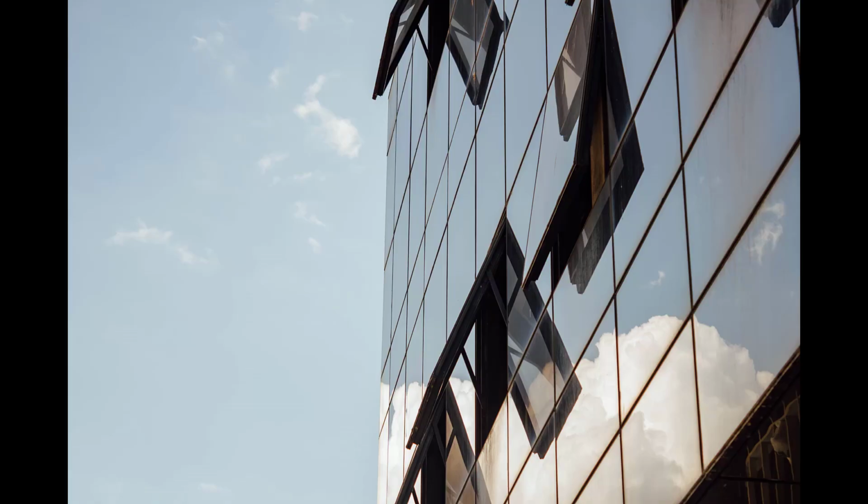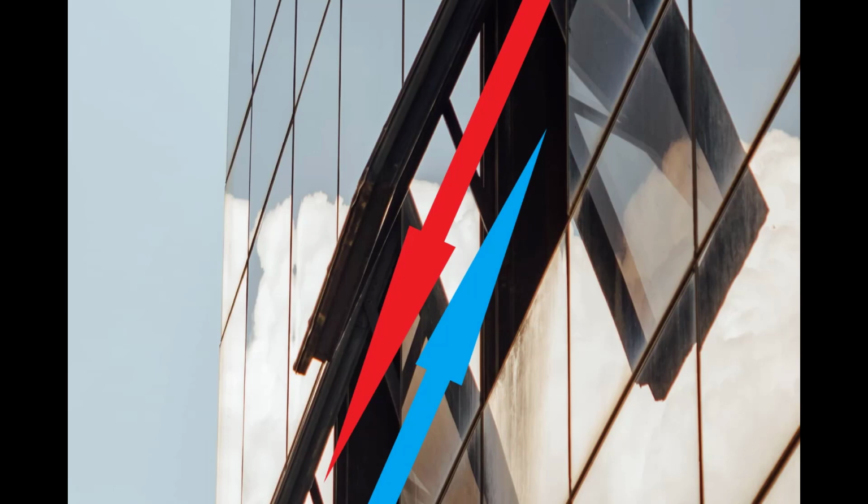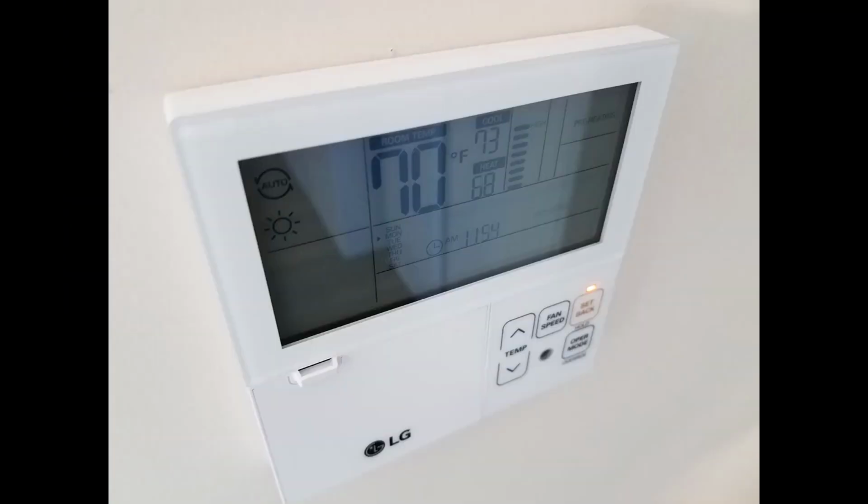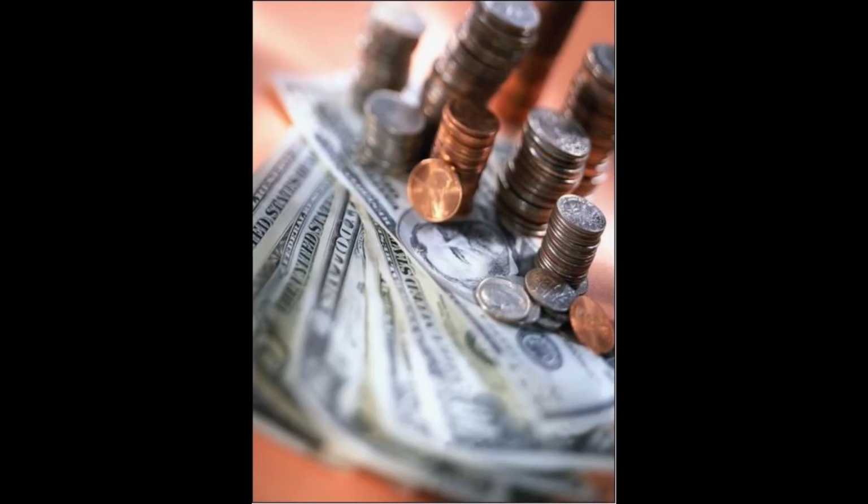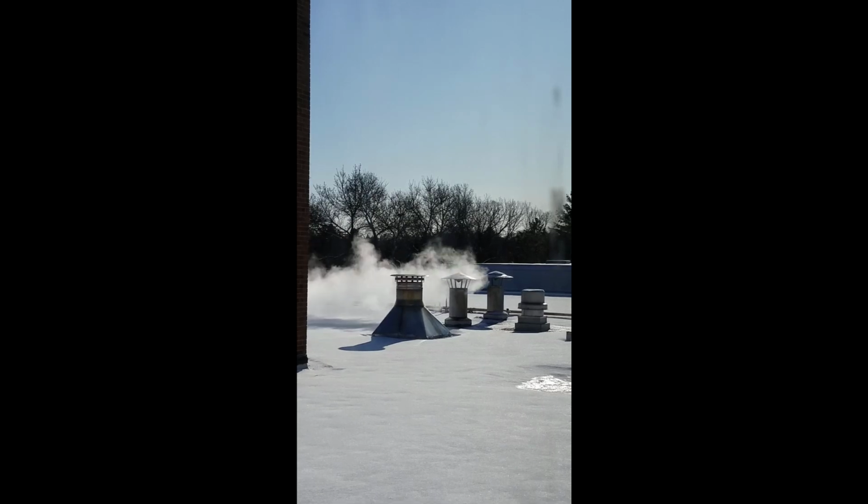Something should be pointed out here that should now be easy for you to understand. What will happen if the room space we've just talked about has a window that's been left open to the outdoors? As heat leaves through the window and cold air enters, the room space will be constantly calling for and receiving booster heat that isn't needed. This is extremely wasteful. It wastes money, it wastes natural gas and energy resource, and it puts unnecessary waste or pollution into the air.